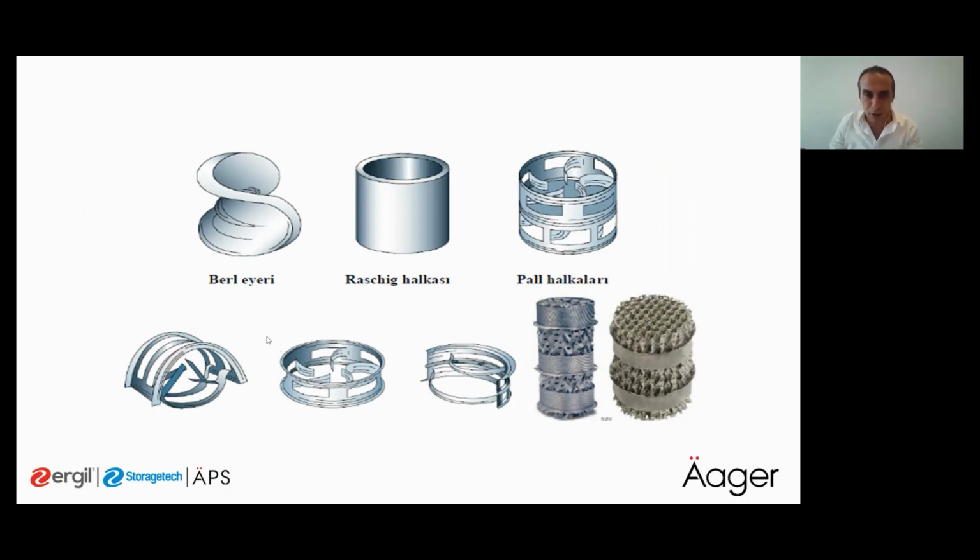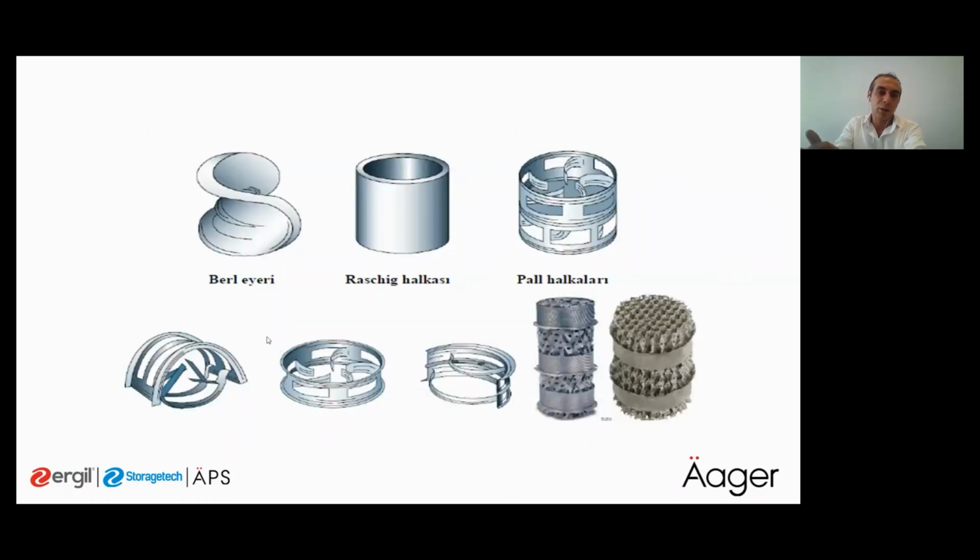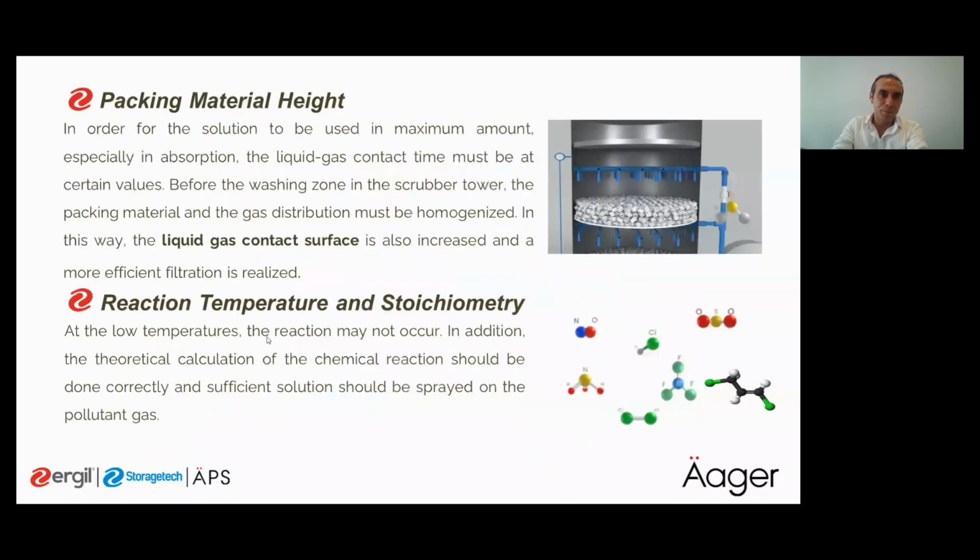Those directly change the scrubber performance, because they change the wetting area. I talked about this one before. It increases the reaction time and increases the surface area between the gas and liquids.